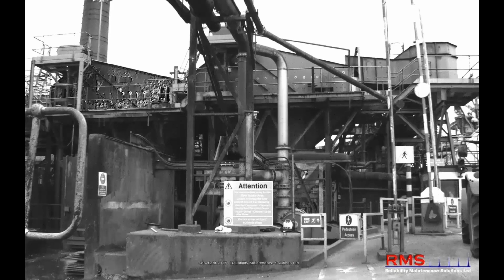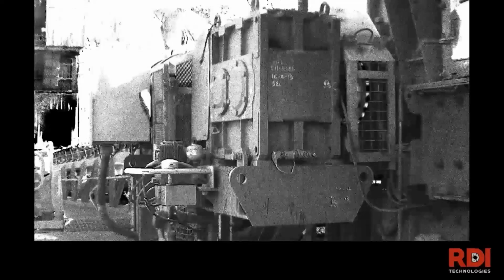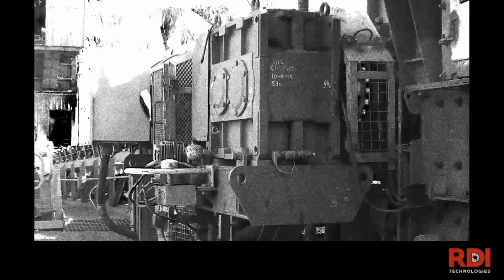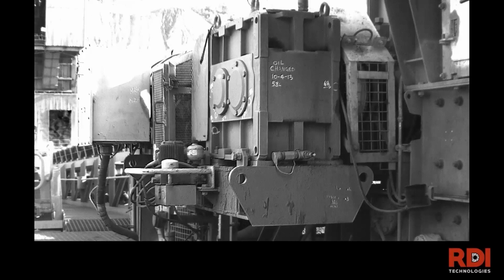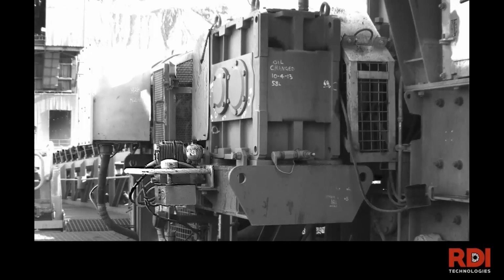So again, what I wanted to do is just demonstrate the ability to show different frequencies, because it's a very important part of this, just to set up the background. Again, we're showing the overall motion of this motor here, and then we can filter for individual frequencies, like the 2 hertz of the output of the gearbox, or say the 25 hertz for the motor, or say something in the background, like the 4 hertz on this conveyor that's bouncing in the background, which actually ended up being the real issue here.